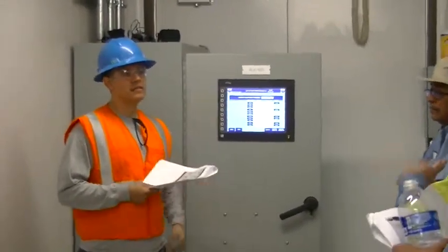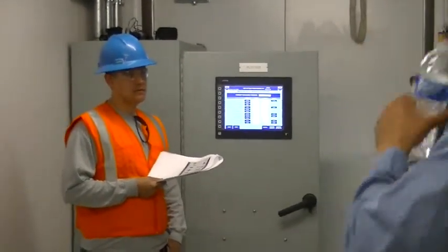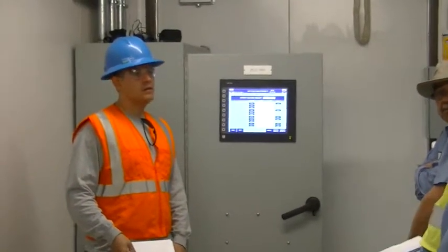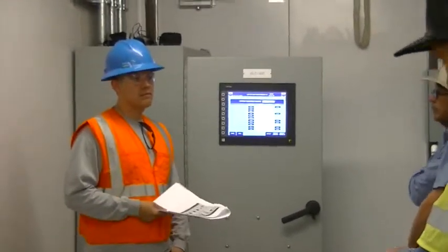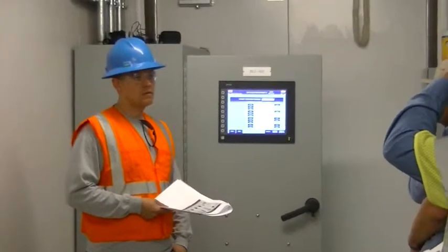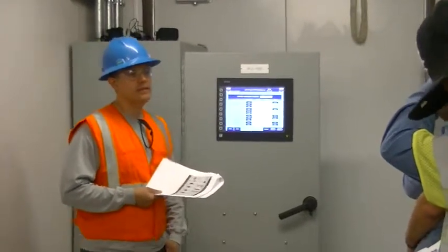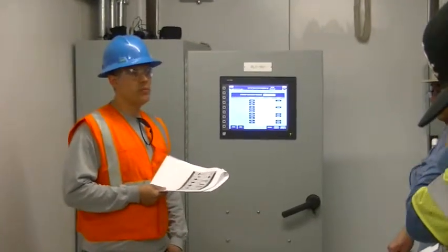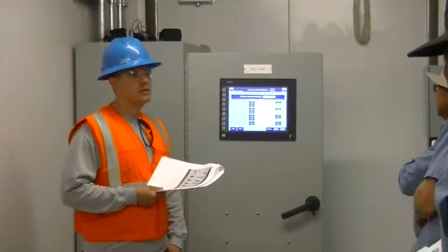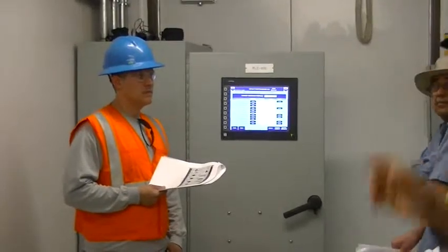Right, I know, but what I'm saying is when the second one kicks out, all the load is on the first one. Right. So it's probably going to ramp up a bit. If they were running at 42 hertz, then it would probably kick up to 60 hertz or something. It'll kick up to try to get to that set point. It needs to maintain the 65 or whatever set point you have the system at, until it gets to 70 and then it shuts off. Correct. So the VFDs keep it maintained at 65.